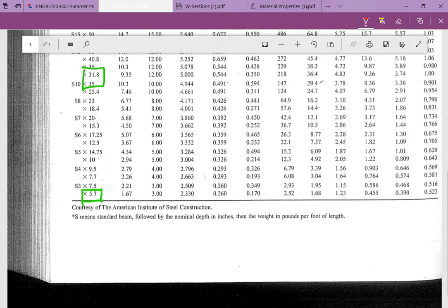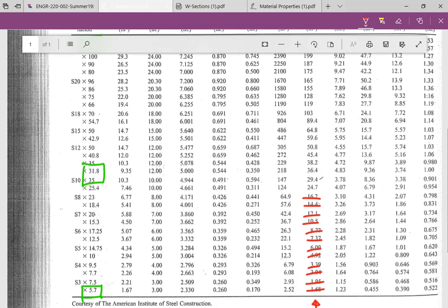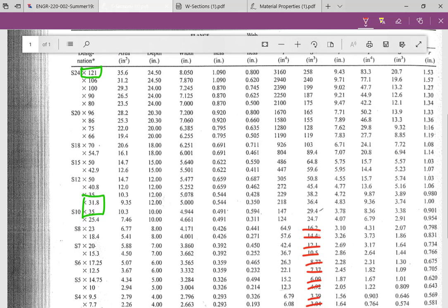So S is this column. So no, these are all too small, too weak. None of those had a section modulus that was good enough. They needed 22 or greater. All of these above there work. So basically it's from this point up that will work for our situation.